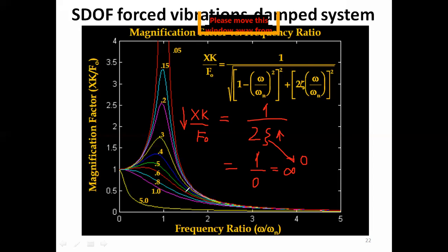But in reality, we know that even if the damping in the system is 0, the system would vibrate violently, but there would be a specific value for the steady state response, that is capital X. Although the chances of failure of the system components at such violent vibration would increase, it doesn't mean that under that condition the system would explode into pieces.